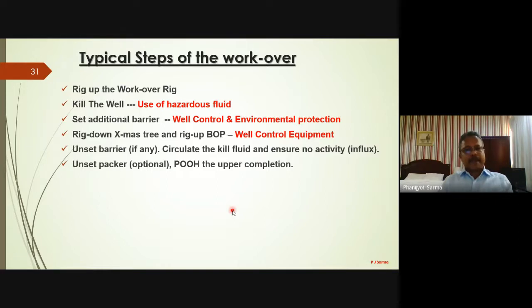Then unset the packer. It is optional, I am putting, because all the wells may not be completed with the packer. If there is no packer, there is no question of unsetting the packer. If there is a packer, then obviously the packer needs to be unset. And then the next step is pulling out of the hole the upper completion.